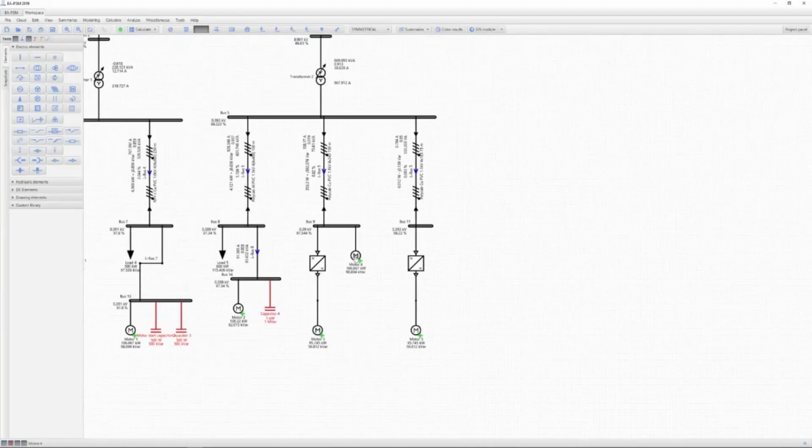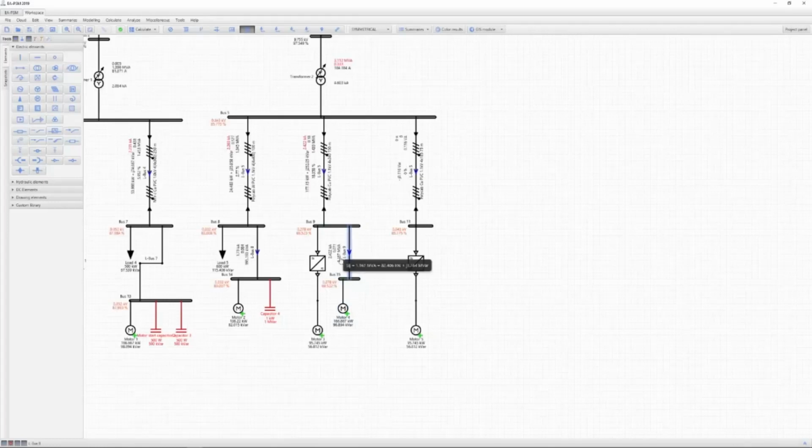So now we're gonna do this again with the same other motor. Add the bus bar, add this. And then we're gonna check the motor start analysis again. Check how much reactive power is generated. 1.6. So now the voltage has dropped substantially. We see that a lot of reactive power is generated here.